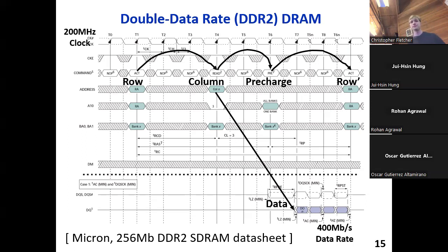Yep, that's exactly right. Great. Okay, so going back to this picture. What this data sheet is saying is you, as the DRAM controller, if you want to send a row address strobe, you set values to these wires in a given clock cycle.